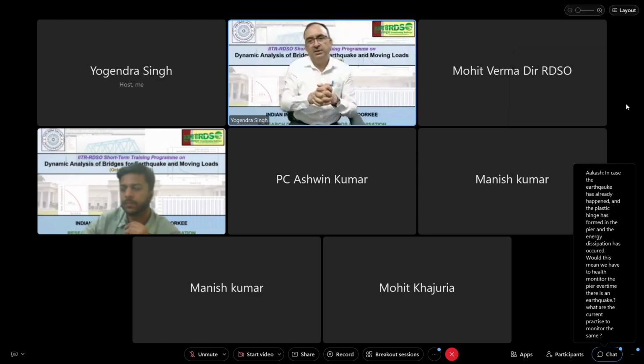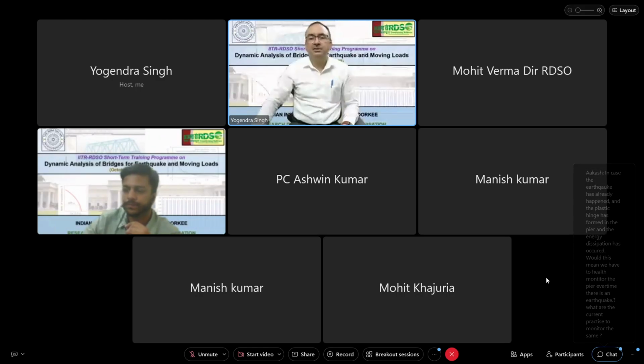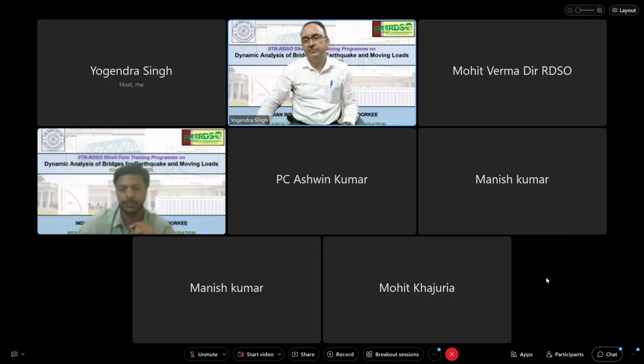You can do that. And to avoid such issues in case of short piers, where you are not getting much advantage or saving, the code says let's not get involved in this in case of short piers up to 30 meters. If the pier is taller than 30 meters, then you go for all this.